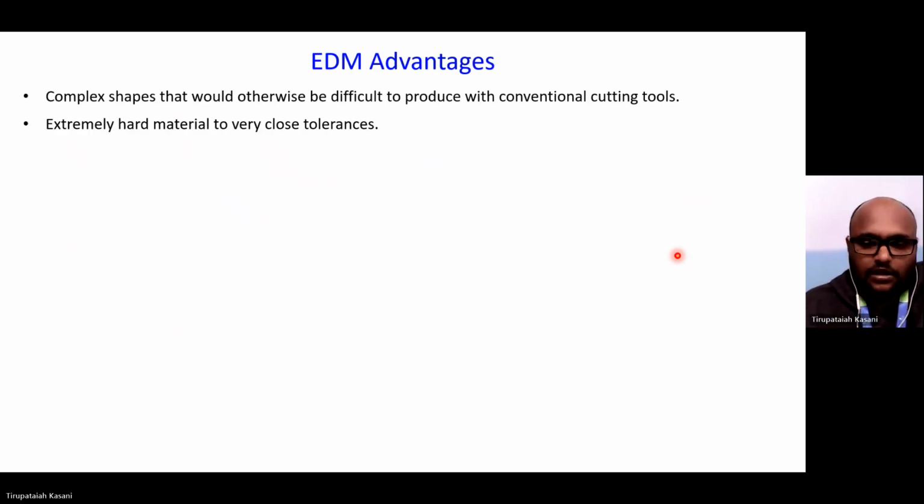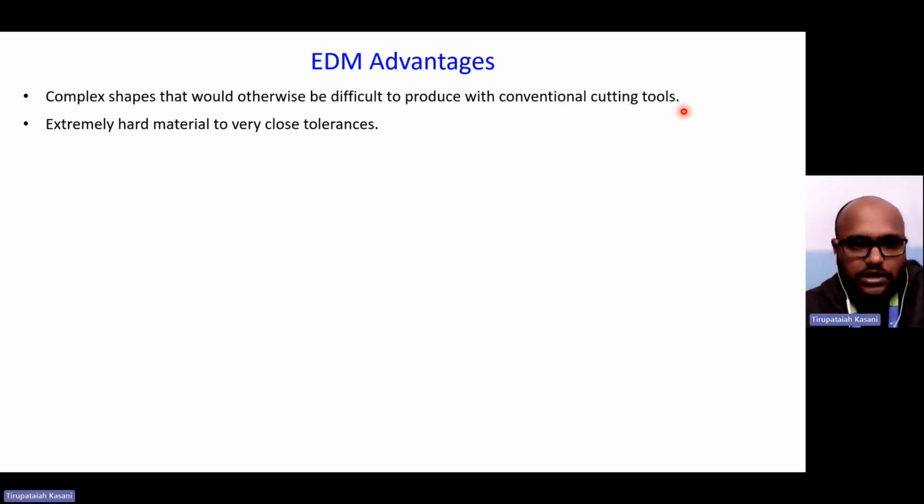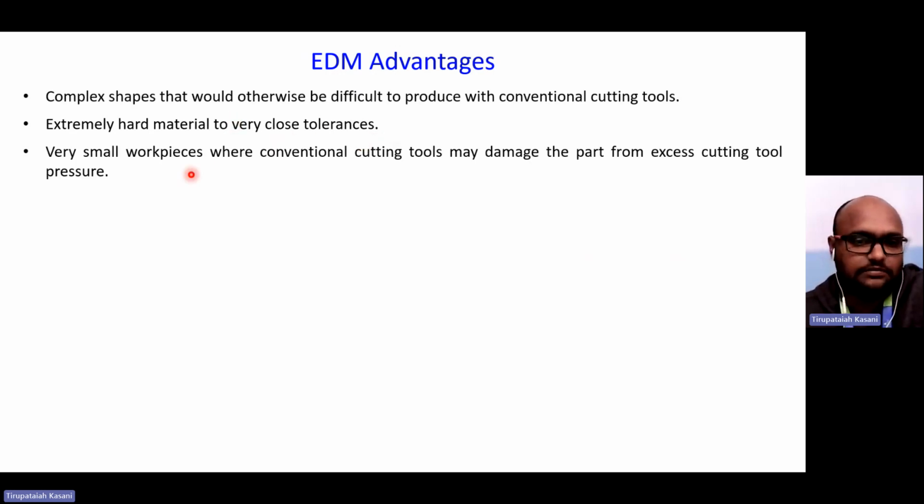EDM advantages: complex shapes that would otherwise be difficult to produce with conventional cutting tools. Extremely hard materials we can cut precisely, to very close tolerances.